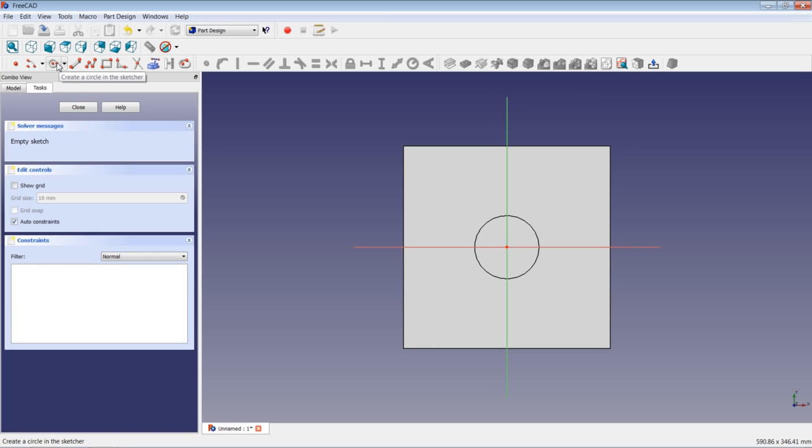Now this time I will click on the circle icon here, and I will show you something. If you move the cursor over an X here, just look at the lower right corner where your cursor is. It will show you a small symbol because, as I said earlier, we had set up in the preferences an auto-constraining, saying that there is an algorithm in the background running all the time. Whatever the algorithm does recognize, it should display.